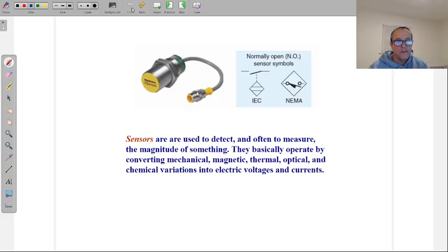They can count very, very high speed things going past the front of the sensor. Whereas, let's say, for example, a limit switch, no pun intended, is limited at how many boxes can I get through there? One box. How fast is this little lever going to come back up? Where's my next box? If I run the boxes too fast, then the limit switch never pops forward. So I can't accurately count boxes. It just seems like one box passed by.